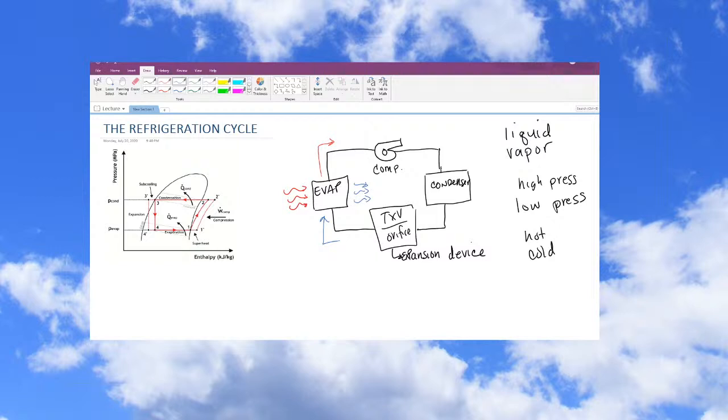Okay, so, but what about this refrigerant? There are some key things to this refrigerant. We're not just taking refrigerant and saying, hey, let's make it cold, because this refrigerant has to undergo that phase change. I talked about that phase change for latent heat of vaporization to occur, to transfer. So if I need that phase change to occur, then I have to do certain things. One of them is I need it first to be a vapor. I'm sorry, a liquid.